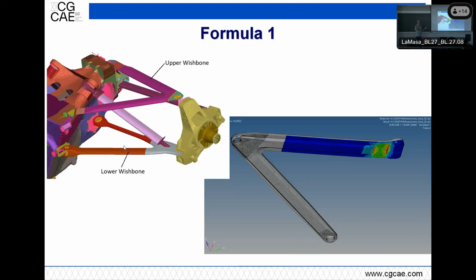Another thing that a stress engineer can be required to do in Formula 1 or motorsport is to analyze failures. So you may have had some failures that were not expected, and you need to investigate more. Here, for example, is the rear top wishbone of a Formula 1 car. It's not this one; this one is here just to show the position. And there is a flexure there. So a different philosophy from how Ferrari was building it, but still a shell model, which was giving quite a high reserve factor.